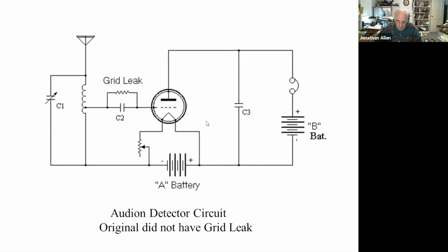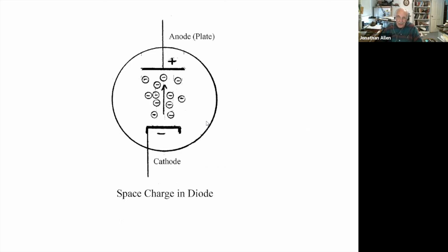The positive anode of the diode accomplishes this field, and the anode or plate, and in vacuum tubes we use the term anode and plate almost interchangeably. The anode, however, is not hot enough to emit electrons, so the diode will conduct only when the plate is positive with respect to the cathode, and this is rectification. Simple enough, but there is another, more subtle but vitally important effect, which we call space charge. No, this is not a command given to space cadets.